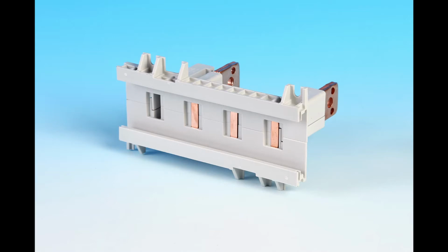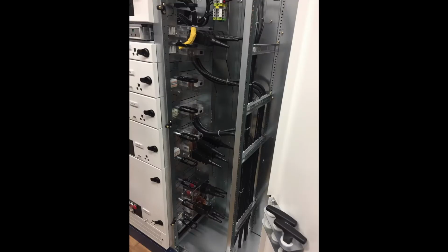Standard cable connection with cover up to 75 square millimeters is foreseen to realize up to Form 4B. Bigger cable dimensions need customer-specific construction and covers. The picture shows samples of how a cable connection can be realized.